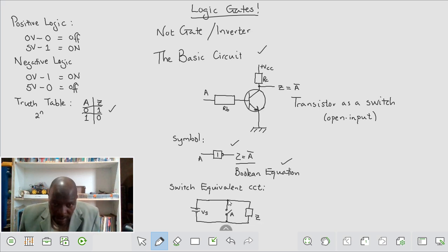Right, but this, however, is a dangerous circuit to draw, because in practice it shows that people don't understand their basics. We've had a session where we looked at what happens if we close the switch here, we eliminate this. When you eliminate Z there, now there is no resistance in the circuit. When you've got no resistance in the circuit, what happens? Let's see what happens with the current. Remember, according to Ohm, I is equal to V over R. Now we are saying we have a resistance. We don't care what the value is. In this case, V supply.